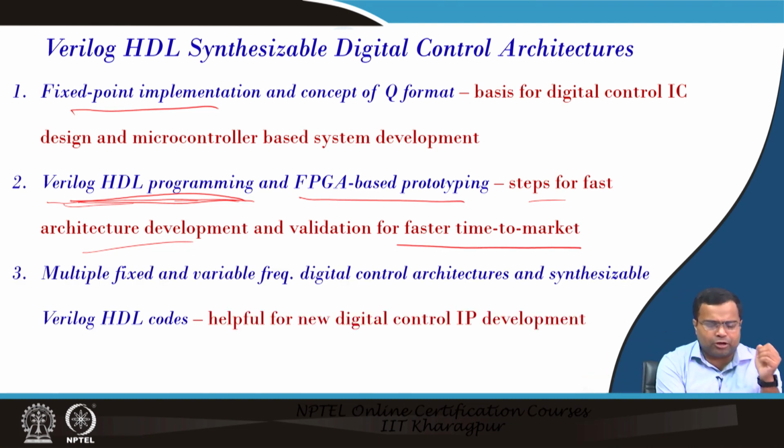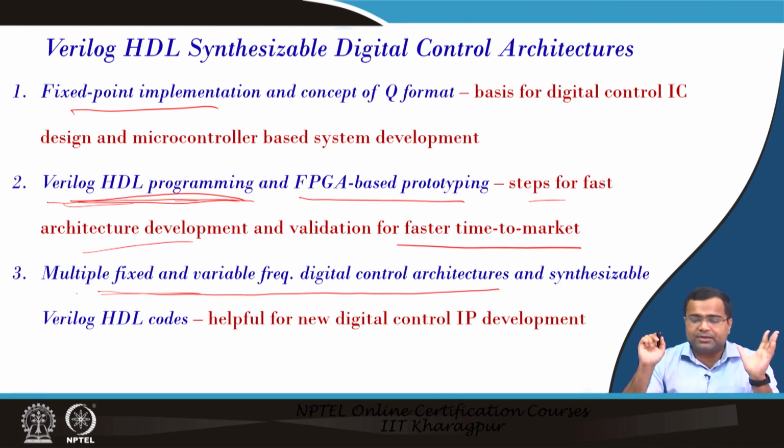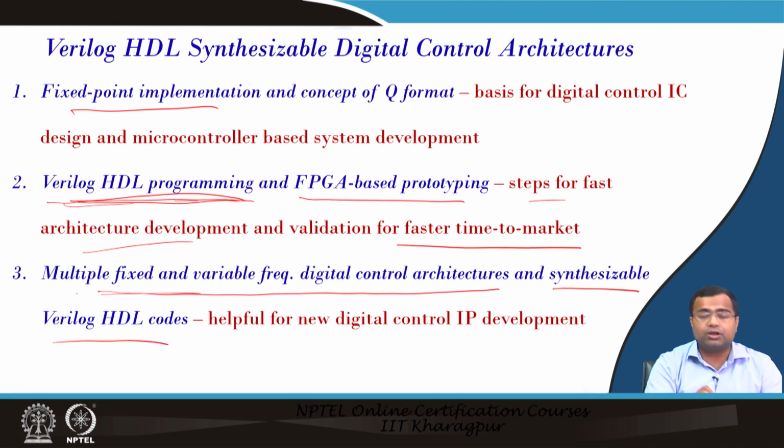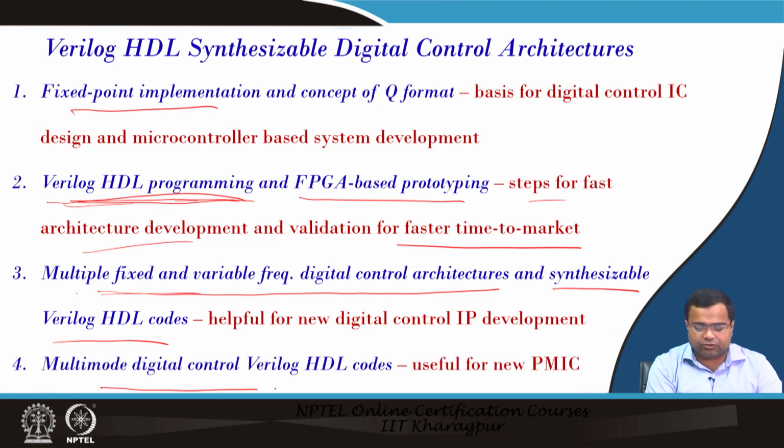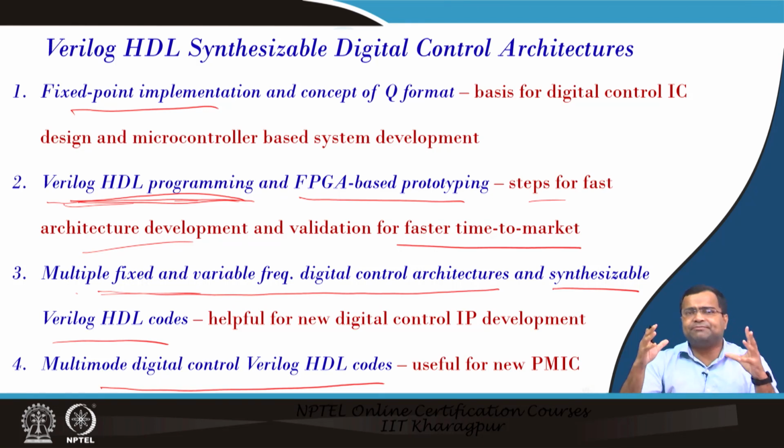We have discussed multiple fixed and variable frequency digital control architectures. We have developed multi-mode control, variable frequency digital control, fixed frequency digital control, and spread spectrum techniques, and we have developed synthesizable Verilog code. This can be very useful for new digital control IP as well as IC development. Finally, multi-mode digital control using Verilog code can be a very powerful solution for future IC development, PMIC, which can offer fast transient and high efficiency for a wide operating range.